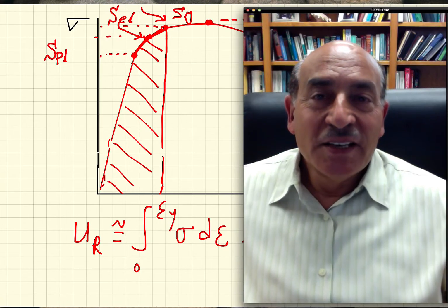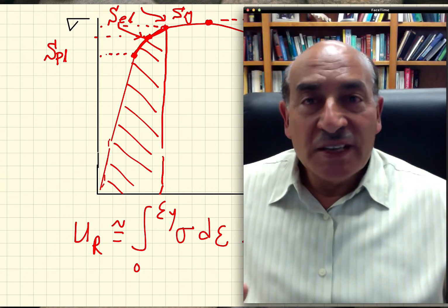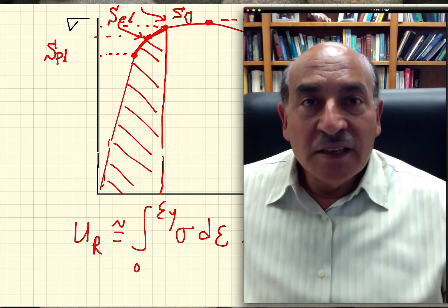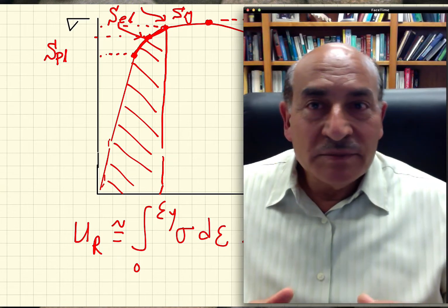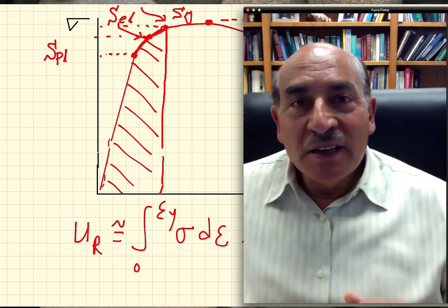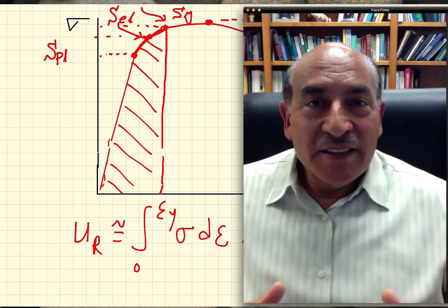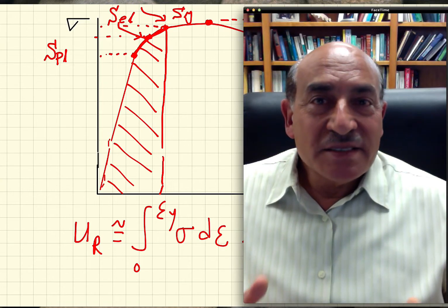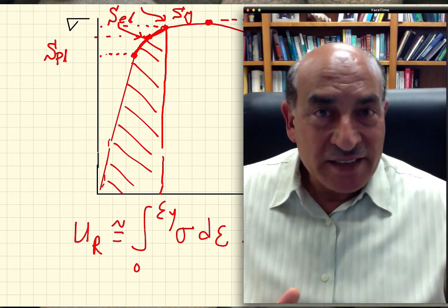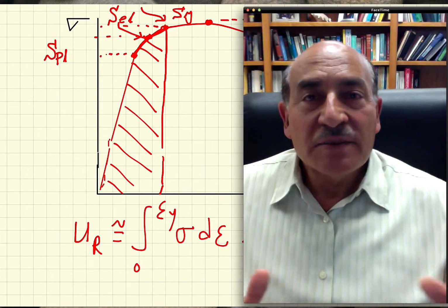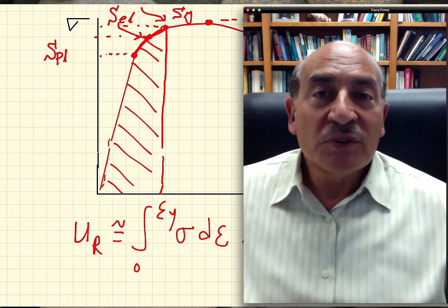However, if you describe someone as tough, that person can take usually higher levels of forces, and bounces back with some broken bones and some blemishes on his face, and therefore we can call him tough. That's the same idea for materials. Resilience describes elasticity, and toughness describes the entire energy that can be absorbed before failure.